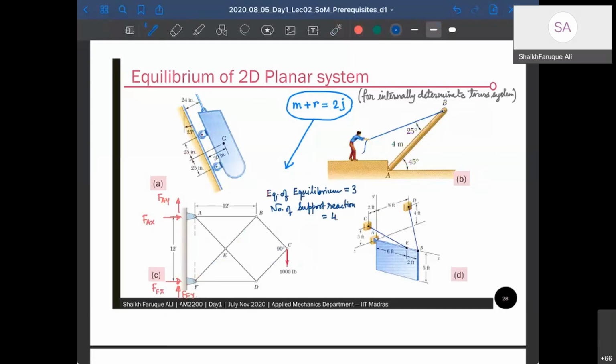Yes, sir. Yeah, who said that? Jai. Yes, sir. Yeah, Jai, can you tell me how do you solve it? We assume forces to be axial along the members, and then we solve the 3 equations on every body. Every member we will solve for 3 equations. Means we can, but we shouldn't. We should not. Now, how do you solve for these 4 reaction forces?